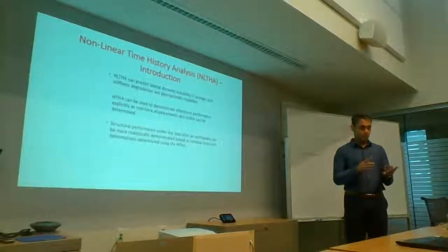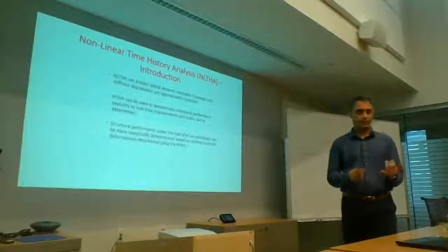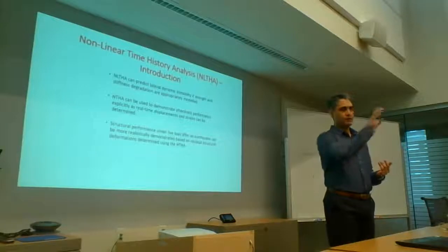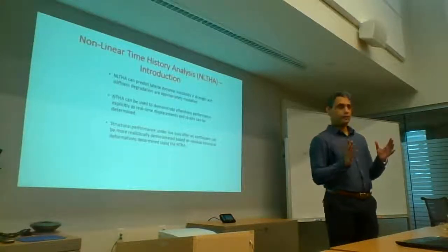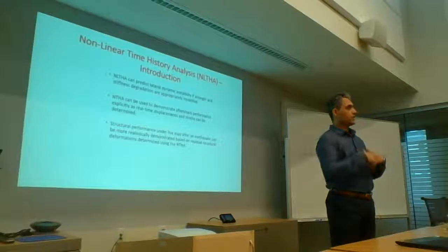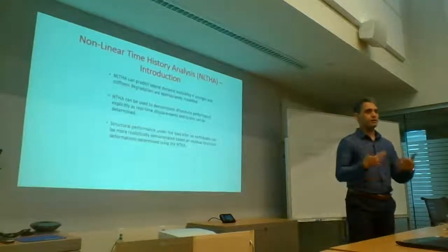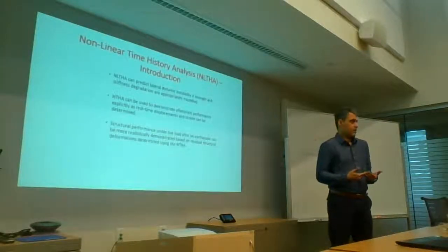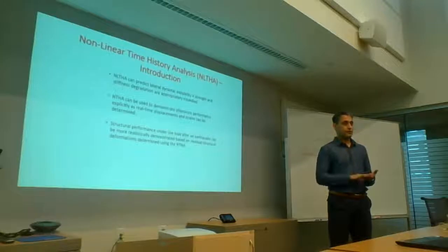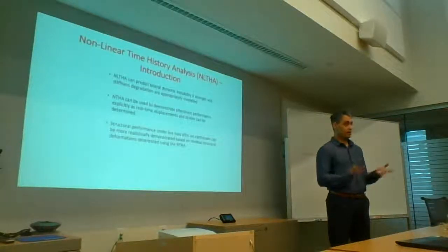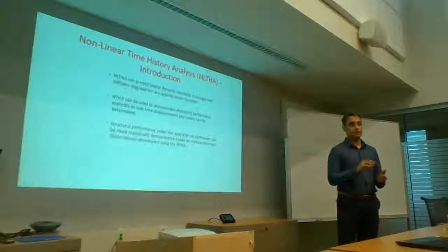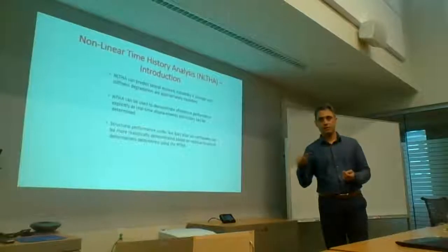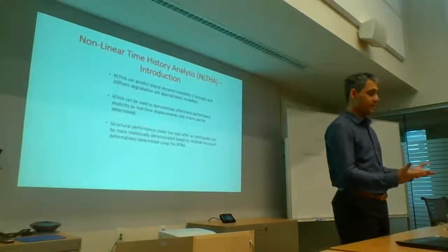Okay, so if we've modeled rebar rupture, if we've modeled buckling, if we've modeled concrete crushing, all of that is in there, and we can capture the degradation then. And also perhaps if geometric nonlinearity is an issue, if you run it, the analysis might blow up at some point. And that tells you that your structure has basically failed, it's collapsed. Be careful, because it might come about as a result of just numerical instability. So you have to be a bit careful in terms of figuring out if it's real or if it's just spurious because of some modeling issues. But it is able to capture that.